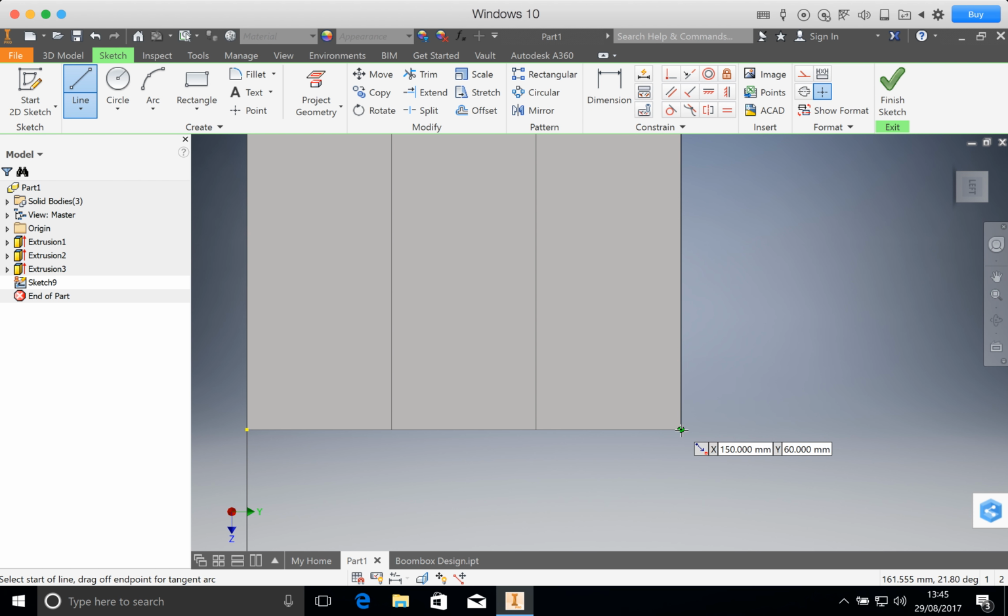Select this bottom corner here, like that. Click and let go, and then move your cursor. Do not click and drag. Then come up and make sure your cursor is selecting the back line here, and click once. If you do that correctly, your line tool should continue as a line tool, like that. And then come down, and so you're not clicking and dragging, you're just moving your cursor down to the bottom left, and then click on that bottom left corner, and then come back and rejoin the original place where you started and click there. We've now created a triangle there.